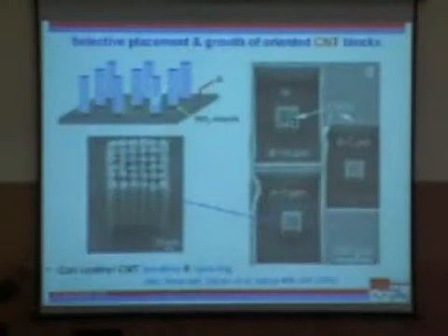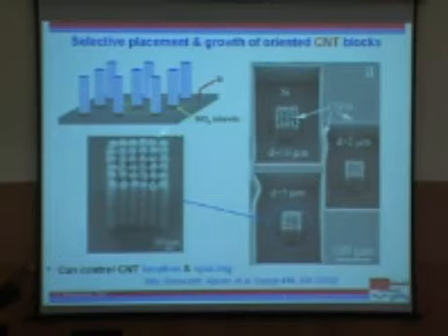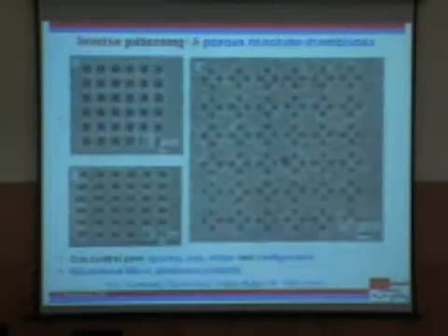The true power of this particular method of growth is that, suppose I provide enough surface area on the side as well, now I can actually get two-dimensional growth. Okay, and actually by extension I can get multi-directional growth by just chiseling the silica surfaces, because the carbon nanotubes inherit the topography of the silica. All right, and if you had noticed earlier, there was no growth laterally, and that's actually quite an important point which I'll touch upon later. Okay, so here I'm just providing a solution: I provide more surface area and I'll get growth like this.